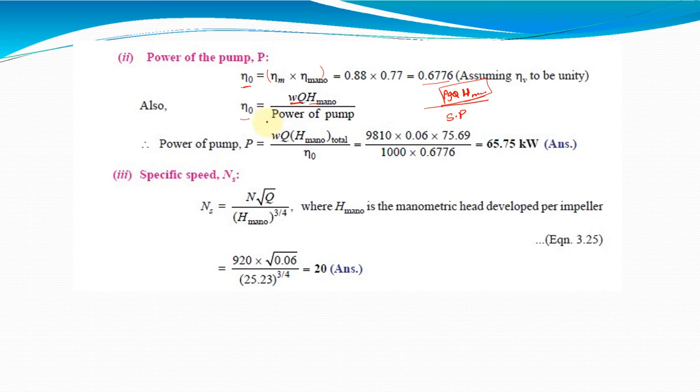So the power of the pump will be w Q H manometric divided by the overall efficiency.